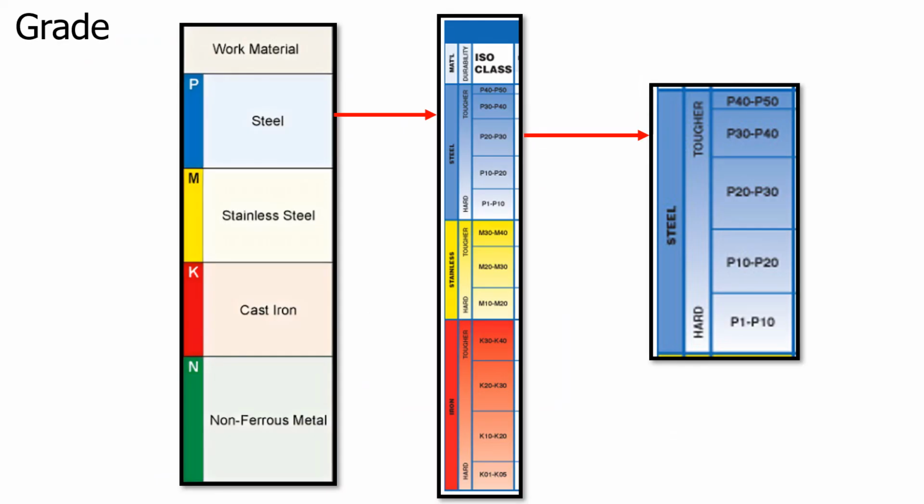I need to order some replacement inserts from my favorite insert supply, which is Kennametal. Obviously, I'm using their catalogs, and I'll be using their catalogs in this example. I'm going to be machining a steel casting. It's going to be pretty tough. It's an intermittent cut, so I'm looking at a grade P20 to P30. Remember, this is an ISO designation. I can quote this P20, P30 to any tool or insert supplier.